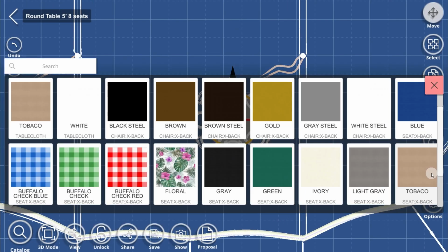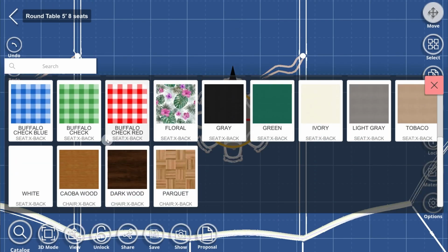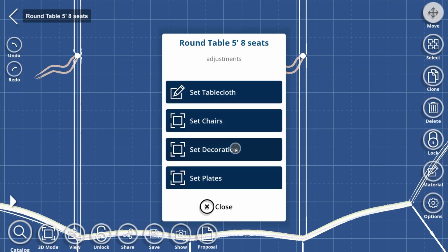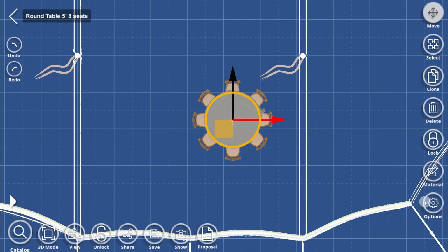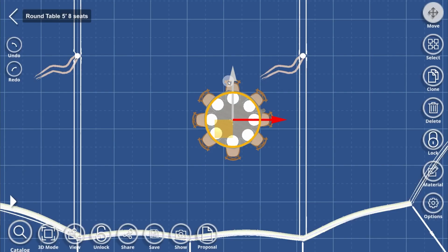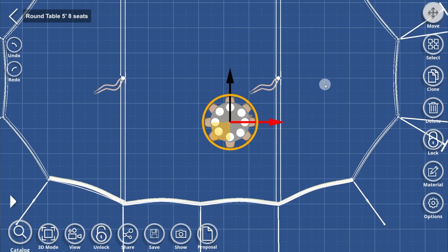You can also choose the materials for the chair by clicking on the Material button and selecting from the available options. Repeat this process for defining the table centerpiece and the plates. Create a single table style with all the features you want for your event. Even in outline mode, when applying materials to objects, they will appear in full detail without deactivating the mode. Remember to exit outline mode once you finish the interior design process inside the tent.